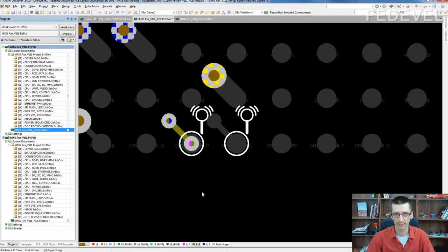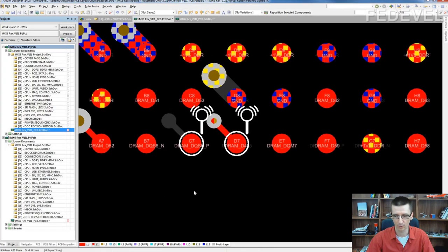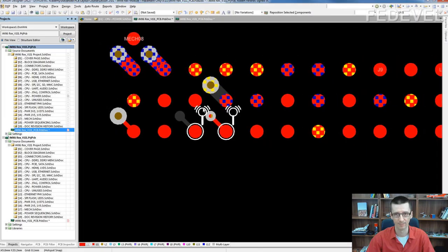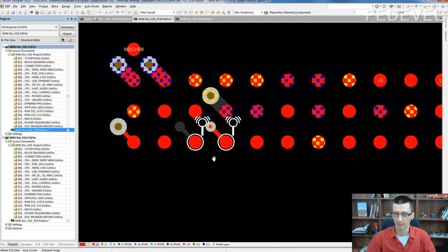It would be very time consuming if you have to do it every time. You can specify this in Altium rules, and Altium will automatically create these micro vias and vias, depending on what layer you are starting and where you are going. I don't use this feature, I normally just copy and paste it.